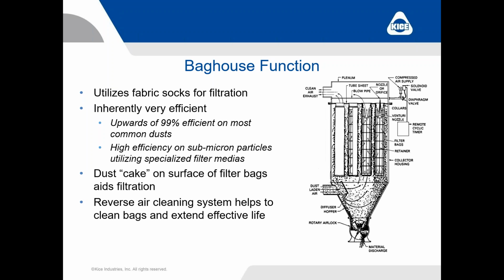So the most common filter bags that we use, and I believe is most common out in the world, is what is referred to as a surface filtration bag. The surface of the bag or the fabric of the bag actually captures and holds this dust and builds a surface layer, or what we call a dust cake, on the filter bag. And that is what adds to the effective filtration. We're actually using the fabric itself along with a small layer of dust that's embedded itself into that top layer of fabric to filter and to clean the air as it passes through the bags and exits through the suction fan.